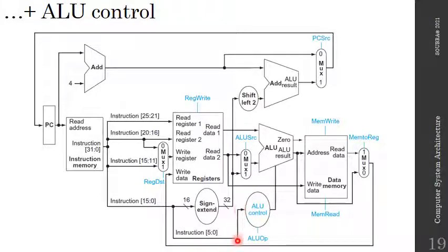Alright, so see the big picture, including the ALU op. So the ALU control will be fed the 6 bits of this funct field, and then something will decide what's going on in here, what kind of operation I'll do in the ALU. So pause the video, contemplate upon that, and this is the end of today's lecture.